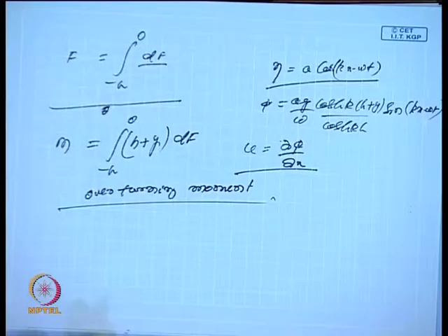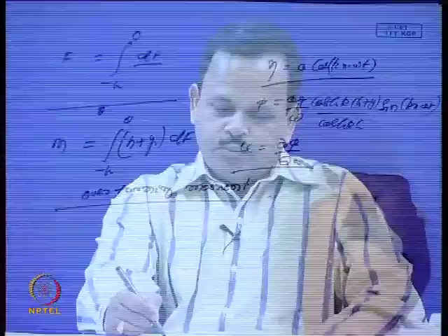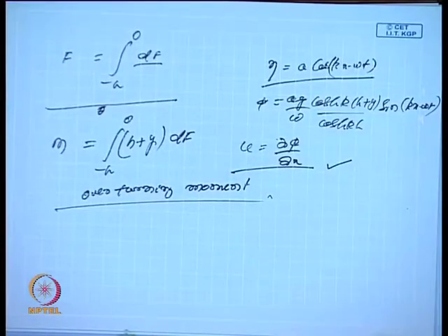In fact, in a large number of offshore structures, several piles are used. So, to calculate the loads on the piles and the overturning moments on these structures, this Morison equation has been used since 1950, and it is one of the most important results in water wave mechanics, particularly for the calculation of wave load on offshore structures.